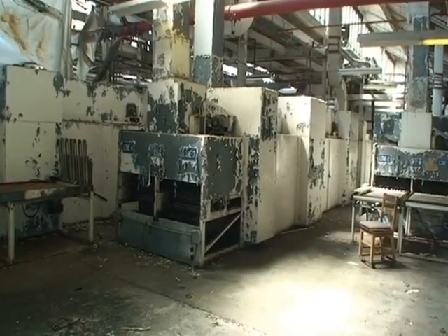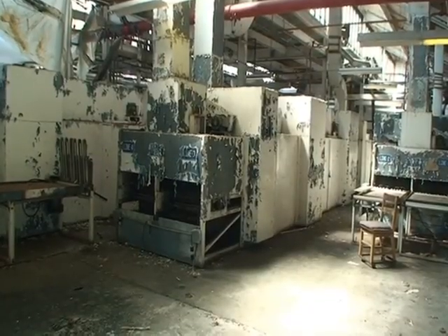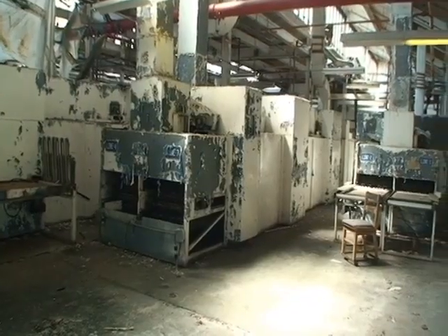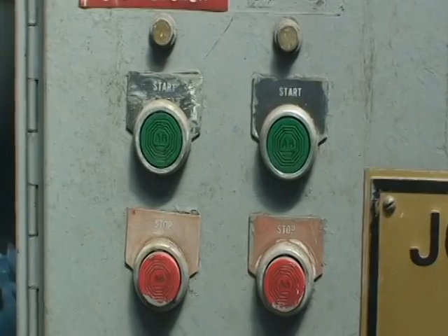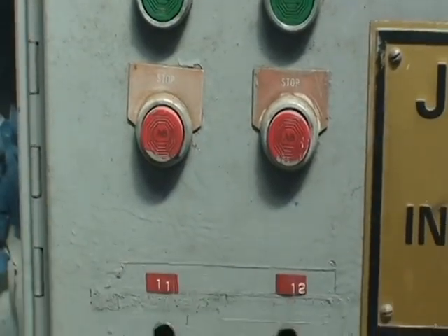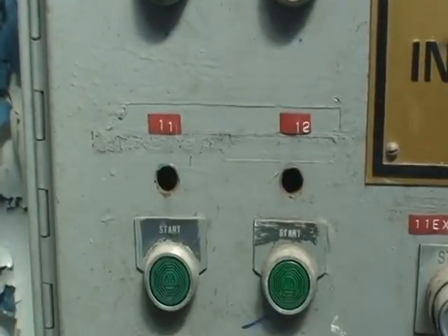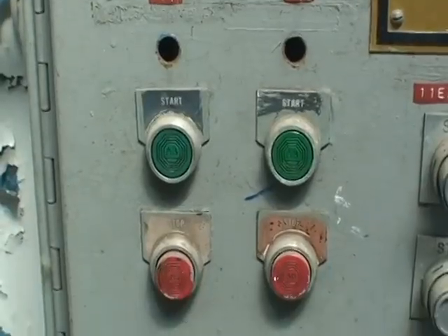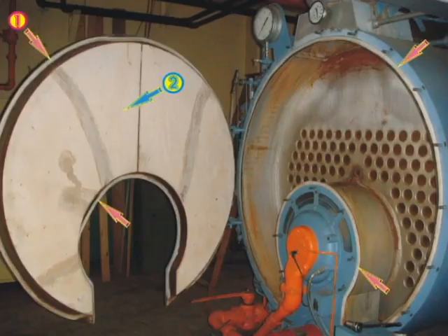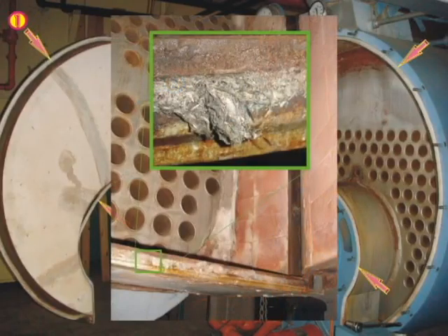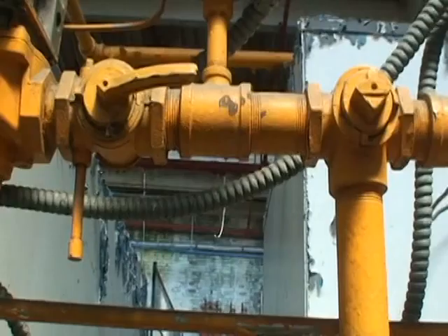Here's an example of some drying ovens. These particular ovens were used to manufacture car license plates. If you're going to be inspecting these buildings or you're going to be collecting bulk samples, you'd need to look underneath the exterior skin on these for transite or some other kind of preformed block materials. It's not at all uncommon to find either transite or the preformed materials, particularly in high heat applications like around ovens and boilers and things like that.